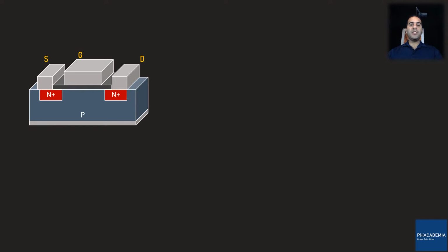As you can see, the two N+ semiconductors are doped in a P substrate. Therefore, we have two PN junctions. As we already know, whenever there is a PN junction, there is a depletion region too. Note that the MOSFET is not yet biased. From the source contact to drain contact, if we look carefully, we can see two back-to-back diodes installed in series.